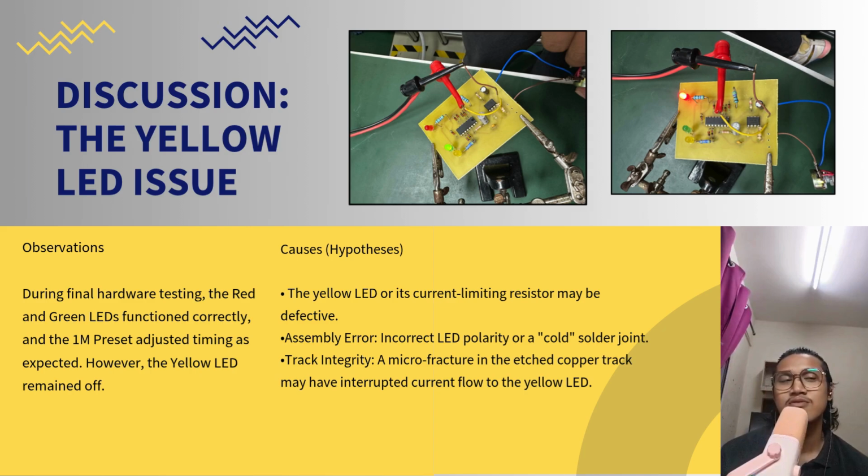So we expect there are several possible causes, including a faulty LED, maybe the resistor, maybe the polarity of the LED itself is incorrect, or a poor soldering connection.